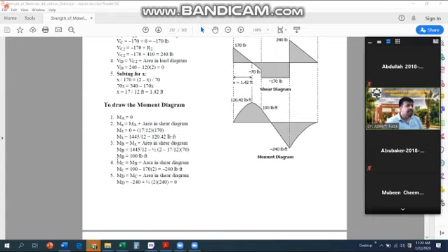Then at C, just like this one, we will find the value at B plus the area of this shape, which is not a triangle but is simple to find. It's 170 multiplied by this distance of 2. So minus 240. So you have another point of minus 240. Then at D, you compute this one, and the answer came out to be 0. So very simply, we had the bending moment points coming out as 0.